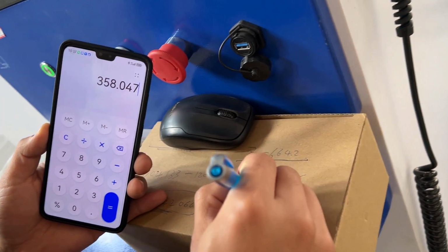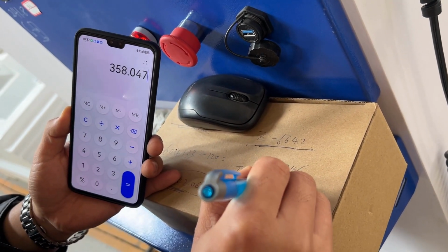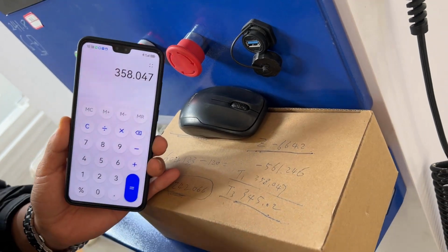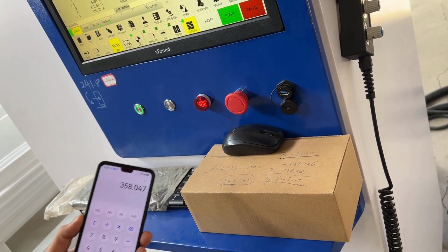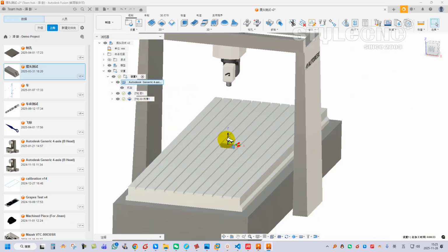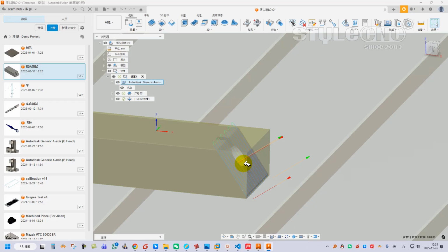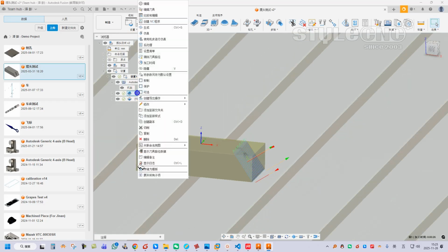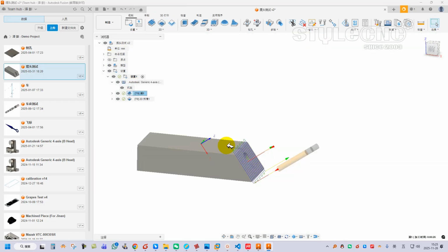This machine's value is 242.066 mm. The other fixed data point is the distance from the bottom surface of the spindle to the sensor when the z-axis is at 0. This machine's value is 664.2 mm.